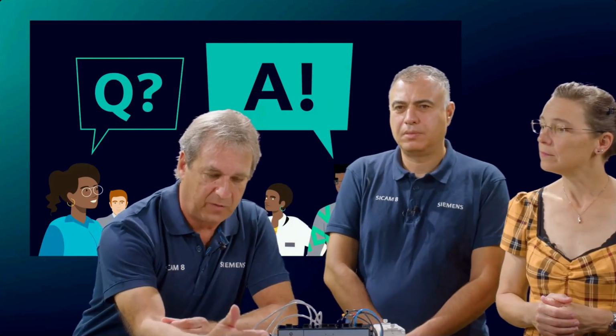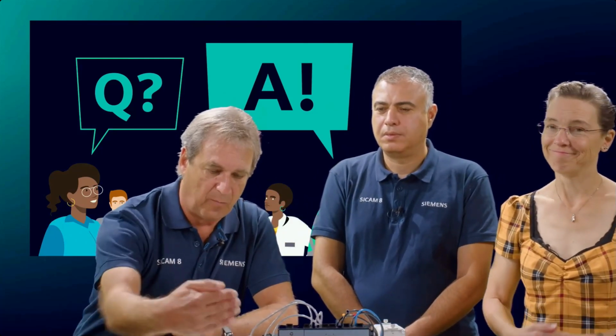THD is available. And why is it so important? Sorry, I have to repeat it. We mentioned it. Normally, such low voltage transformers have a lifespan between 20, 30, or 50 years. If you have harmonics, then the lifespan could be significantly reduced. And that's the reason why we have implemented the THD factor.